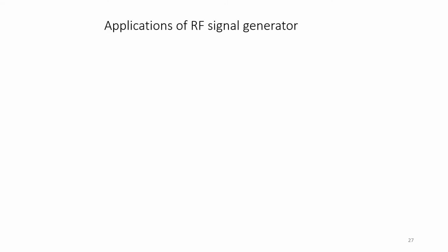For the AF modulation, you can obtain the modulating signal as 400 Hz or 1 kHz. For the power supply, you can use the mains 230 volts at 50 Hz. For the external modulation source, the frequency is 0 to 5 kHz. The frequency error is less than 1%.